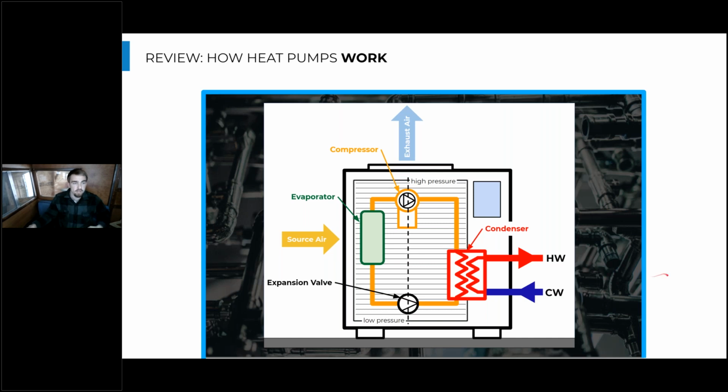So when we think about the refrigeration cycle that is going on in these heat pump water heaters, we can kind of draw a line halfway through this refrigeration loop and think about what's going on either side of it. So up on the upper half of this line that's dividing this loop into two, we have the compressor, whose job is to pull refrigerant out of the left half of this loop and push it into the right half.